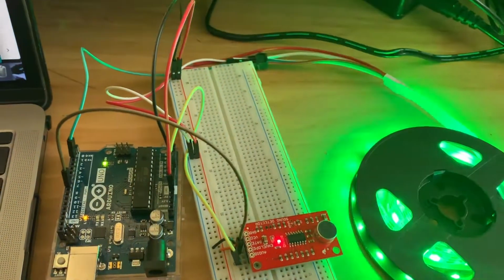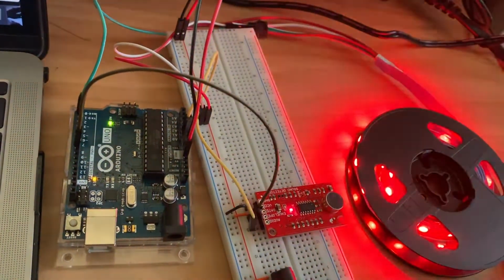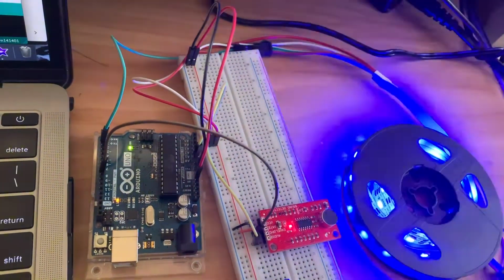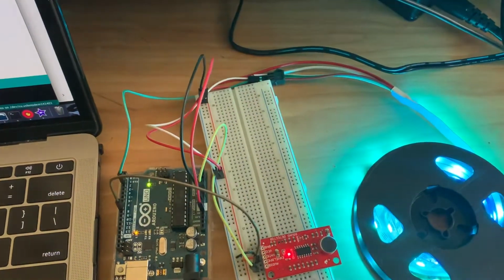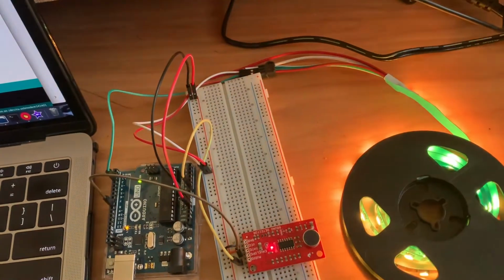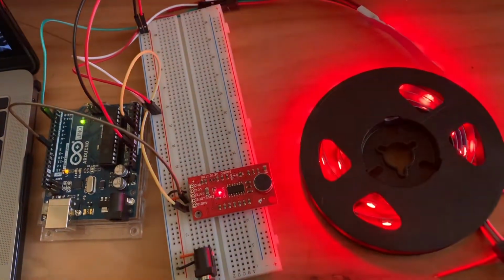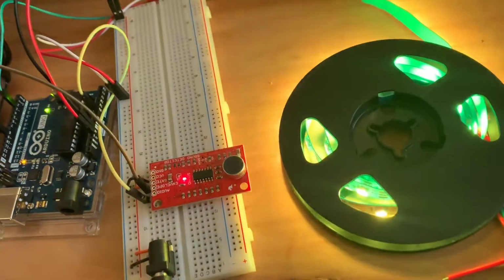The gate is a digital signal, meaning that it's either 1 or 0, indicating whether or not the microphone detects sound. On the other hand, the audio is the actual analog signal that the microphone picks up. I feed both of these into the Arduino as inputs. Naturally, the gate goes into one of the digital pins, and the audio goes into one of the analog pins.